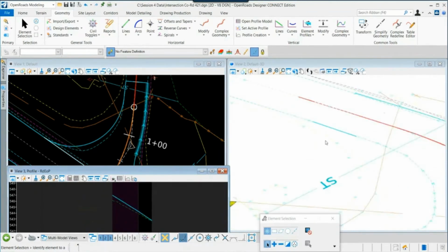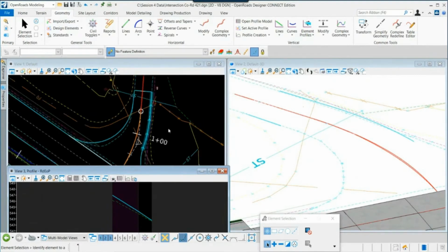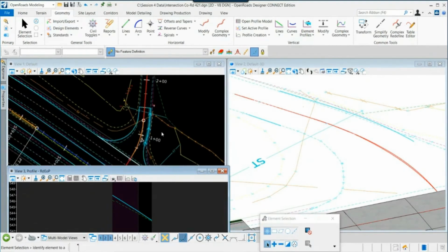But now we've got both edges of pavement defined vertically. We've got a definition for both edges of pavement, okay? And again, think about where we're going here. The process I am working toward is to define the pavement first, horizontally and vertically, construct the terrain model of that pavement. I'll build the pavement layers from that terrain. Then we'll create shoulders and side slopes around it.